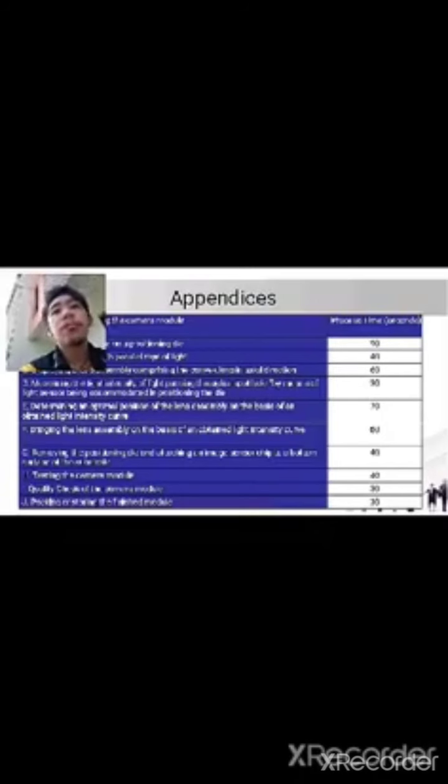Before we begin solving our problem, there are a few things that we need to pay attention to. First, make a precedence diagram and determine the cycle time. Using the largest operation time heuristic, determine the most efficient production line. And last, determine the line efficiency and the smoothing index.